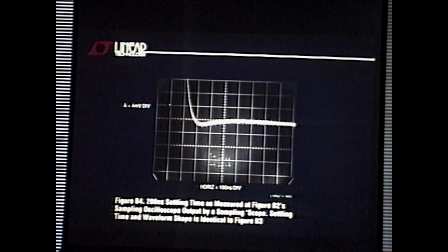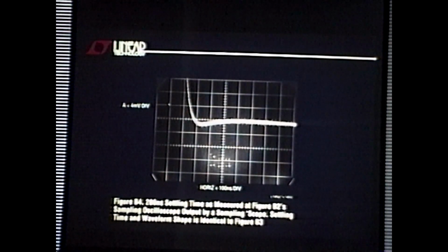Here's another way to measure settling. I basically went and got a sampling scope. So I replaced my homebrew sampling stage with a no fooling sampling scope, in this case a 1S1 plug-in. That plug-in is a single trace kind of thing, but take it for granted and believe me that the events initiate here.